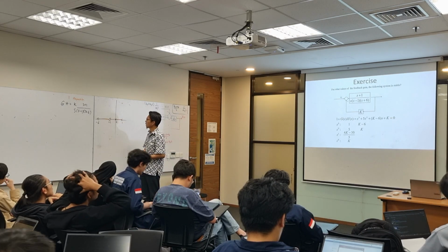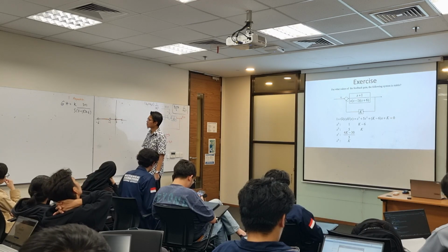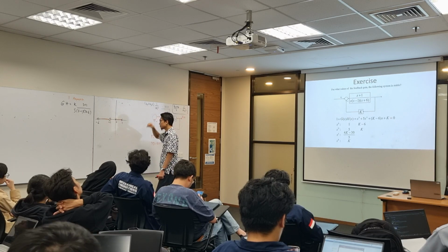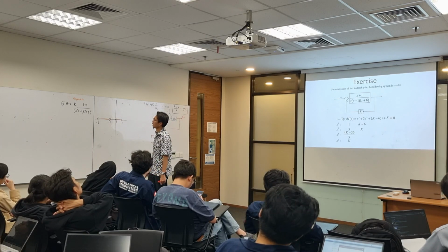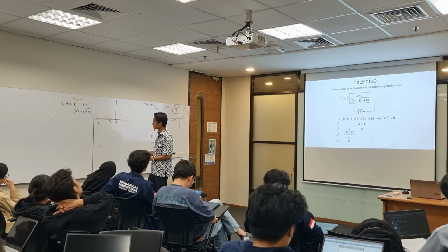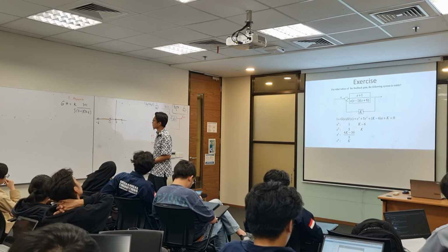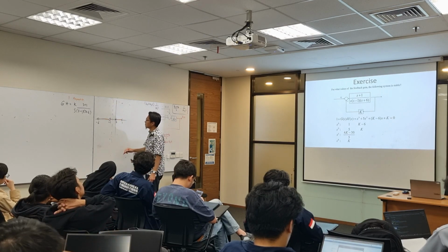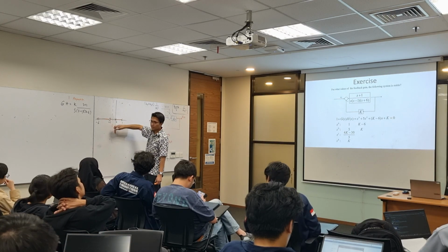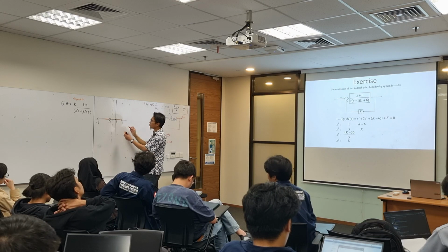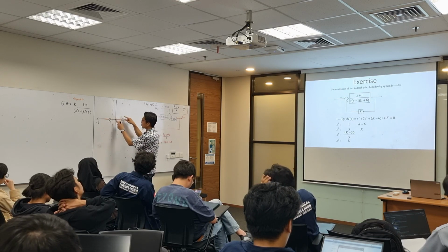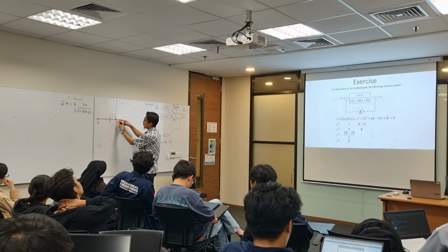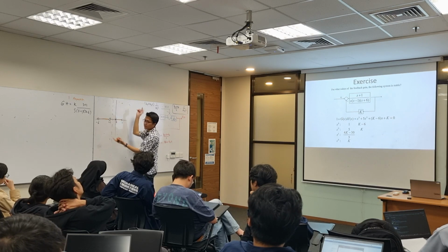And then we will have, how many asymptotes? 3 minus 1, so 2 asymptotes. If it is 2 asymptotes, then the asymptote angles will be plus 90 and then 270. For sure, the root locus that will go to the asymptote is the root locus coming from here. They will go here and then they will break away and then go to the asymptote.